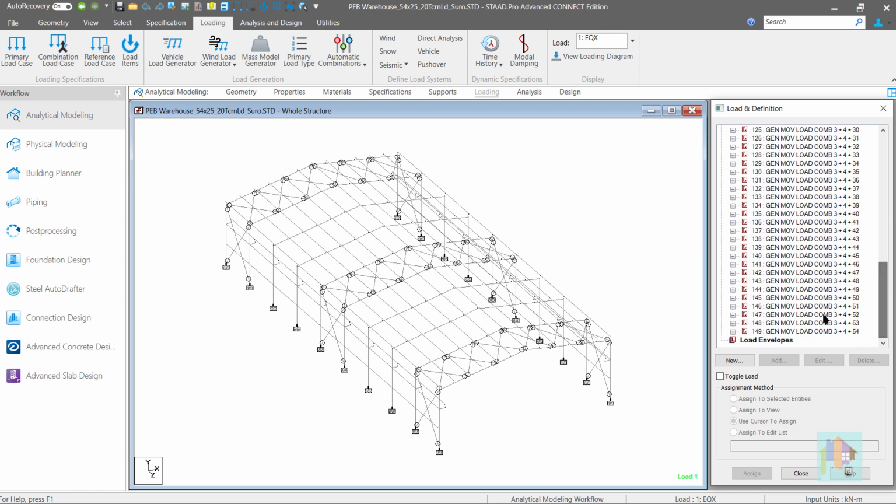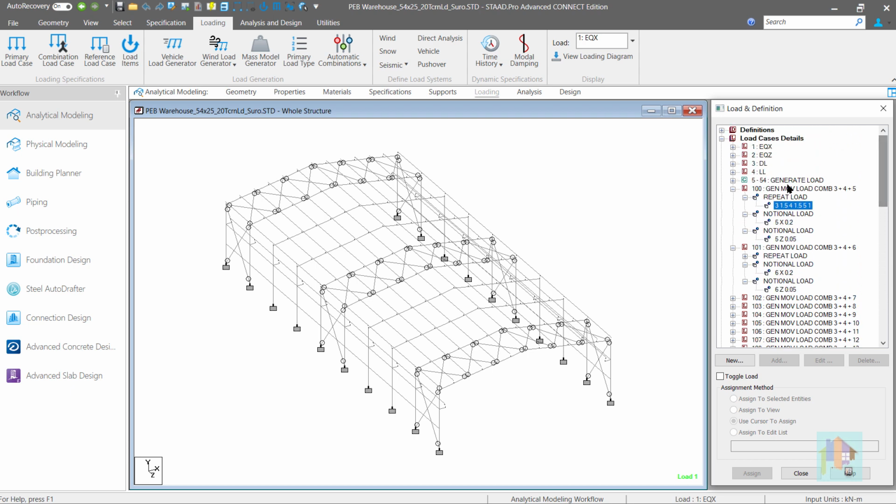Using this type of automation, we can easily minimize our manual effort. Just create the primary and moving load case, then use this tool to generate the rest of the combination load and load in the horizontal direction. Now we can use the analysis result of this combined load for column and gantry girder design.